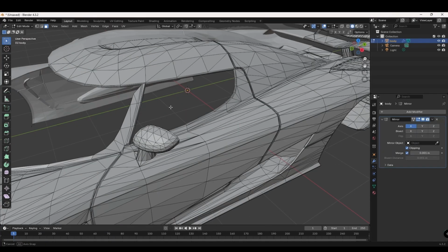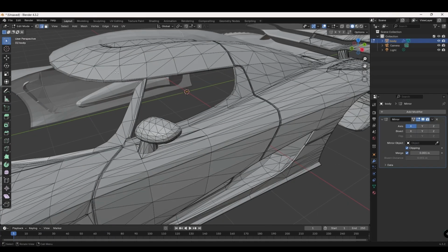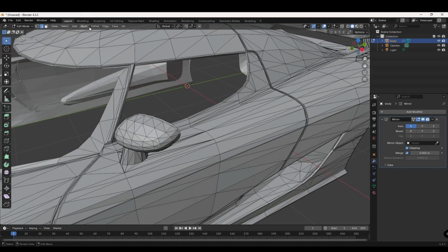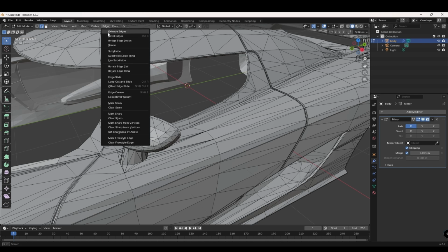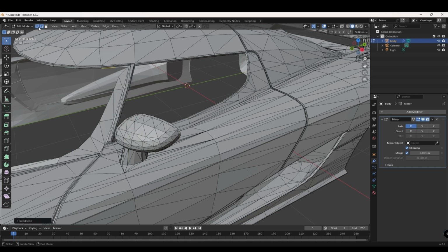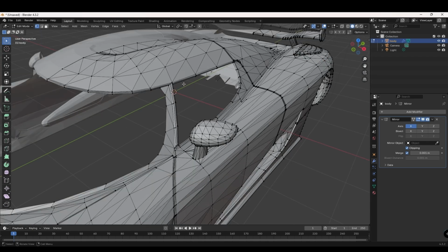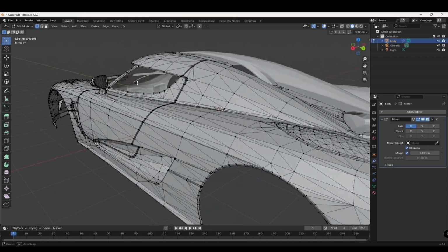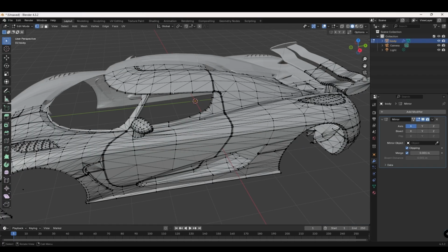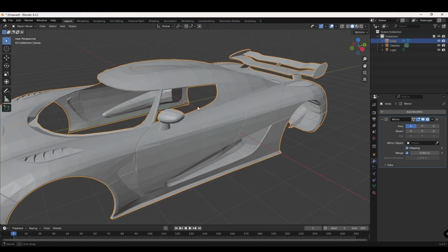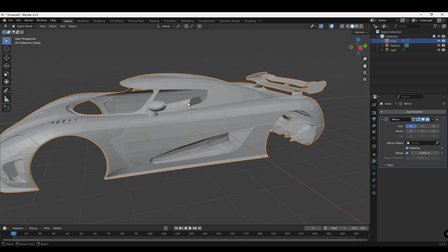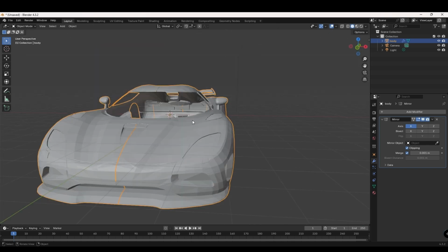Here we can see this has left the frame a little bit thin at one point, so we can select a good edge, split it, and then select the vertices to add a small face back for extra thickness. Now we have a pretty good shell, but it is just a shell. It needs some thickness added to make it usable.